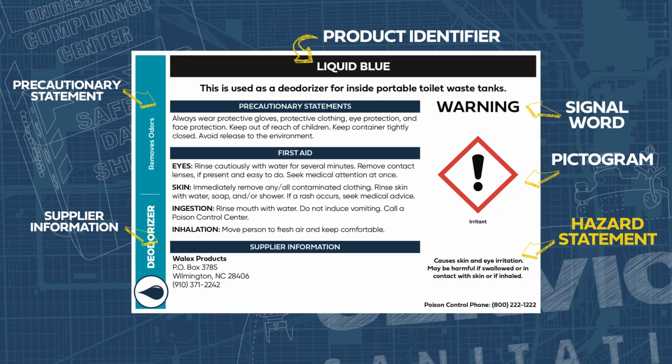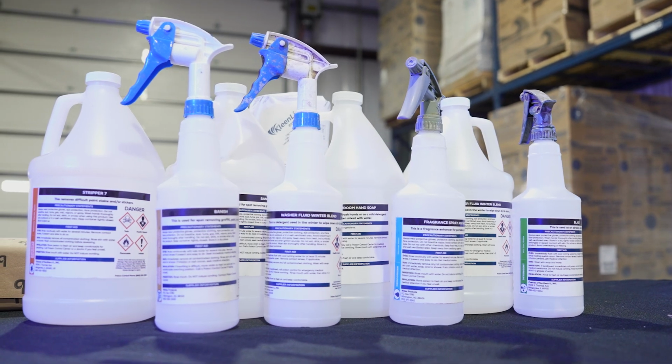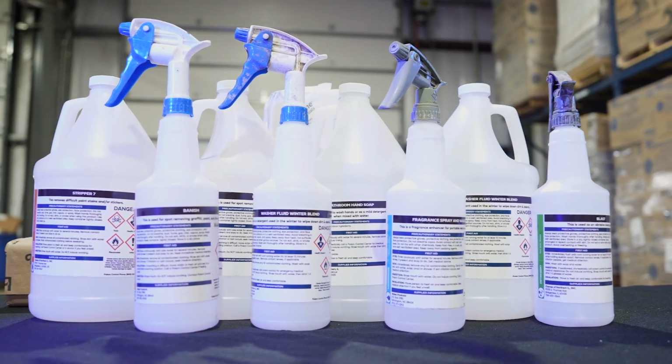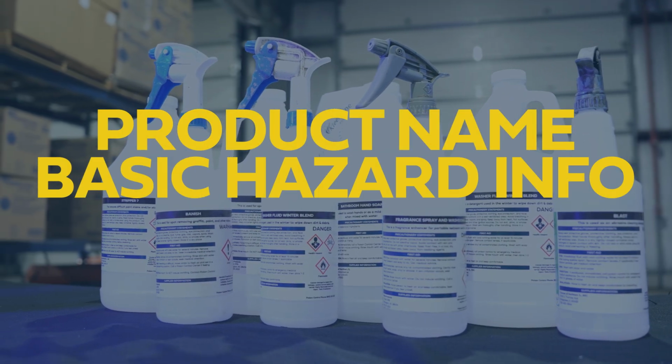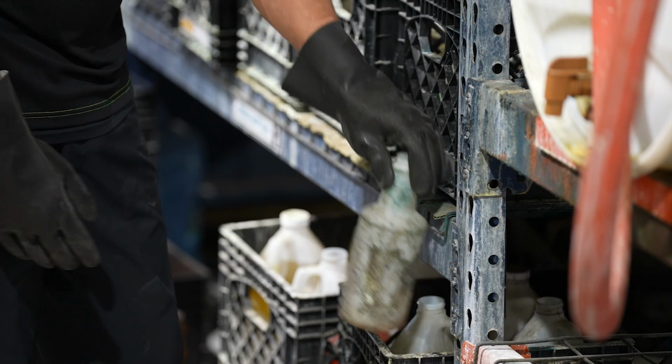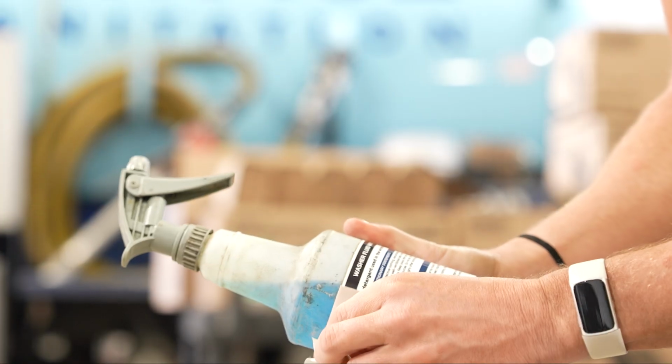The hazard statement on a label pinpoints exactly what dangers the material poses using standardized language. The precautionary statement offers clear steps for staying safe and handling accidental exposure. Finally, supplier information provides the supplier's name, address, and phone number, ensuring you can quickly reach out with any questions. Any chemical containers on service sanitation property or in our vehicles must always be labeled. Labels should include the product name, basic hazard information, and any details workers need to stay safe. If you find a container without a label, relabel it before use or contact your manager to see where you can find extra labels.